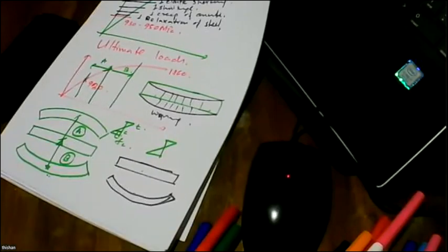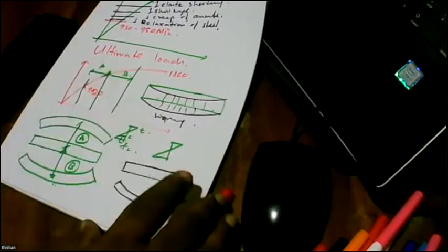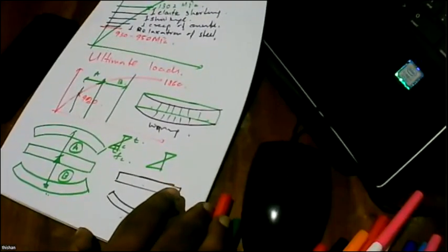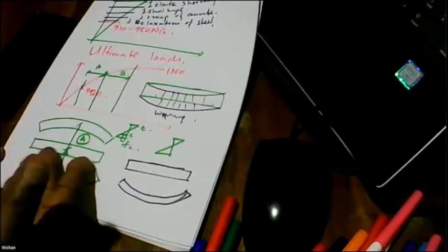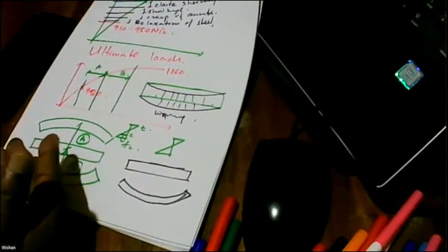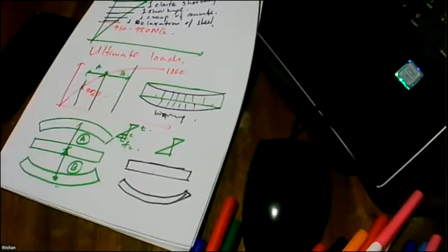So that's why we say, here you can see we are in a particularly advantageous position when it comes to ultimate loads, because unlike in reinforced concrete, we have a huge strain range for this steel, because this is high strain steel. The elastic modulus is the same.